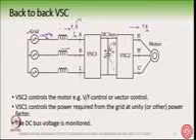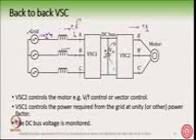But you can make this Q 0, or you can make this Q not equal to 0. You can have another Q. This becomes more interesting: the P from the grid and the P from the motor have to match, otherwise the DC bus voltage will change. But Q from the grid and Q from the motor may not match. It can be different. I have just taken an example that the Q from the grid can be 0, while the motor can take some amount of Q.